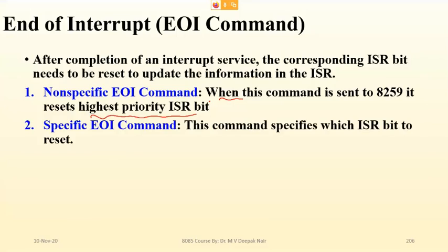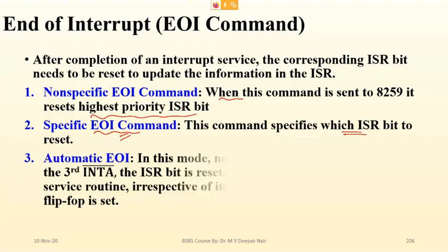Specific EOI: this command specifies which ISR bit is to be reset. In that case, we will tell that IR7 has to be reset or IR6 has to be reset. In this we pass the particular ISR to be reset. In non-specific, we do not pass any specific ISR; whichever is the highest ISR will be reset.